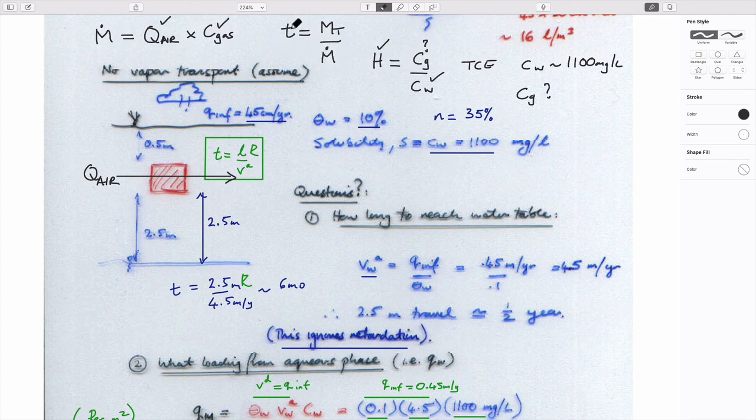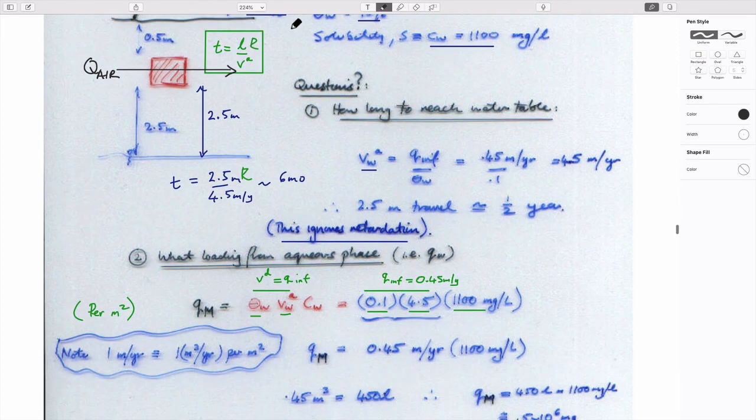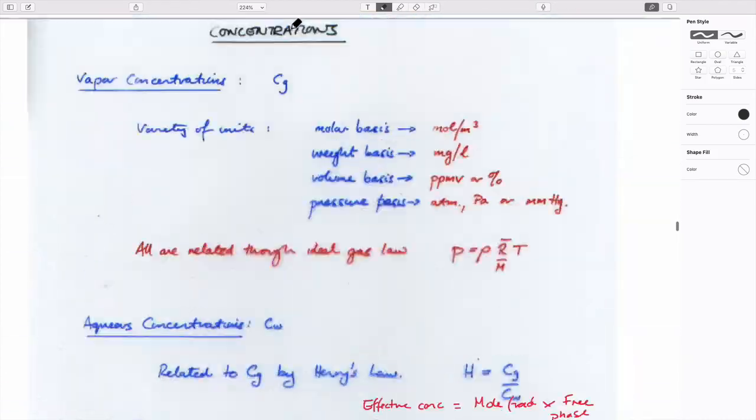And so you can use the same kinds of calculations that we've used before, but apply them in this particular case where, instead of water being the component that carries TCE dissolved in it, air is the component that carries TCE. And of course we'll remove it from the source zone. Depending on how fast your airflow is and for how long you do it determines the length of time it takes to remediate a site.